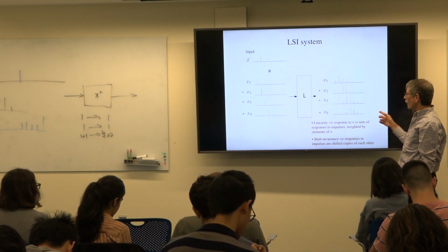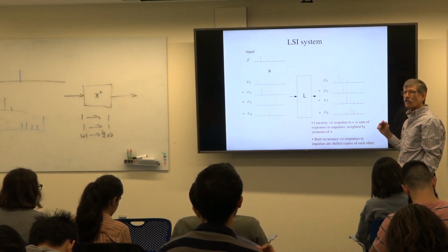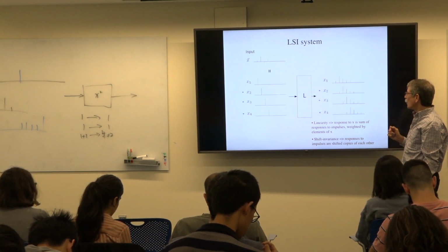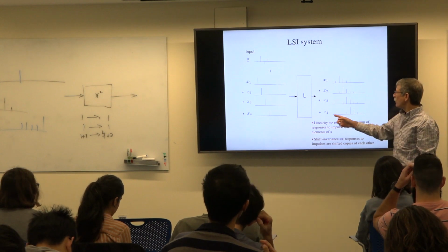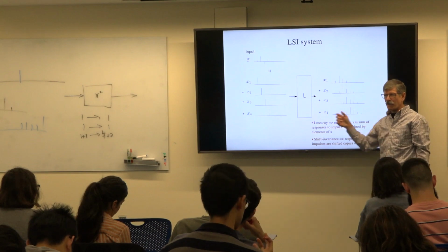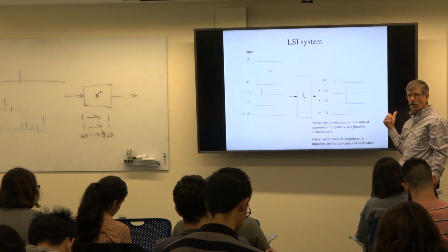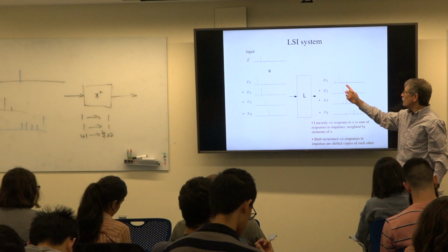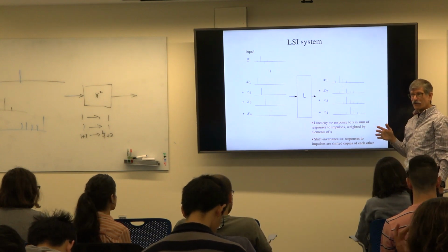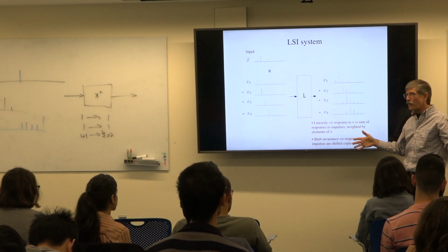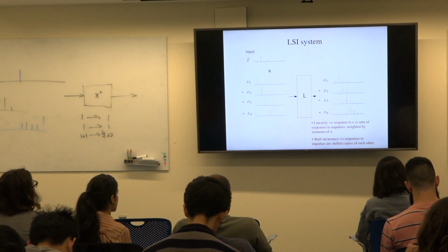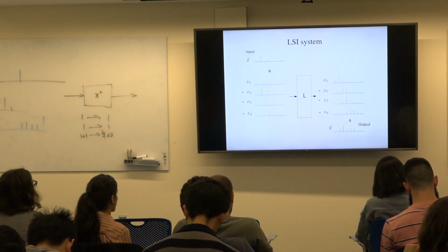But you could just say, well, anything that falls off the end, we just ignore, because we don't know the input then, so it's 0. We're not going to look at the output then. We could extend our input and make a bigger input, so we have the input we actually want to analyze, but we could extend it on both sides with a bunch of zeros, long enough that the impulse response, which is what this is, doesn't fall off the end anymore. So you could avoid the boundary effect by just acting like you have a bigger input. So there are various things around that. But other than that mathematical nicety, the math goes forward.